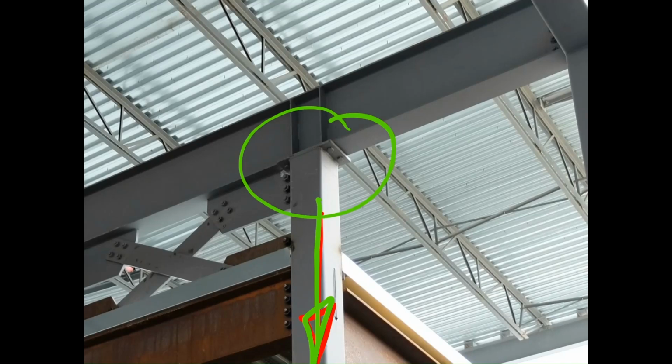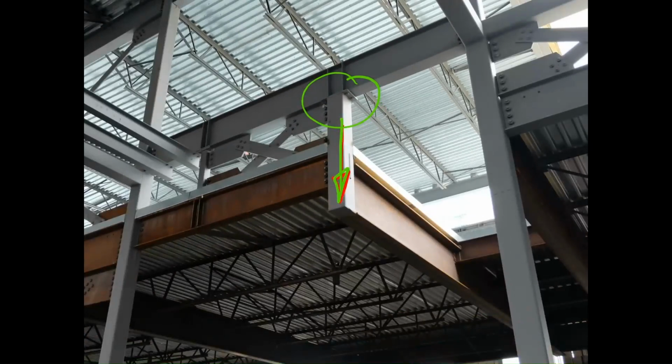Now, the problem that makes this difficult is that when we have a hanger, I'll draw it like this, and a plate, and we've got a tension force acting down on it and bolts here, when the plate is really, really thin, the plate is going to want to bend. We're going to get additional contact forces. We're going to start to apply a teeter-totter kind of effect, and we're actually going to be amplifying the tension on the bolts to a higher level than what you'd think would be present just for the applied force.